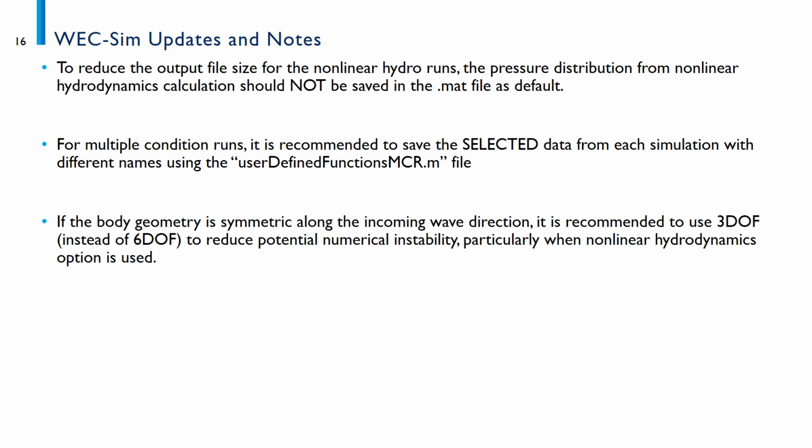Additionally, if the body geometry is symmetric along the incoming wave direction, it's recommended to use the 3 degree of freedom constraint instead of the 6 degree of freedom constraint. This will reduce potential numerical instabilities, especially when nonlinear hydrodynamics is used.